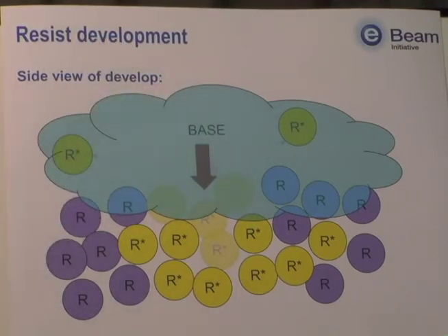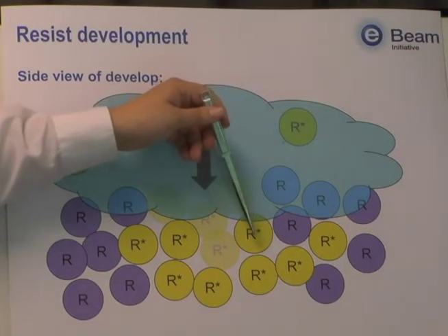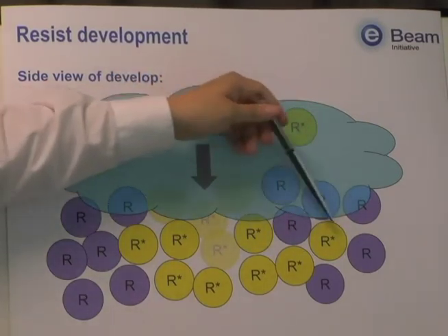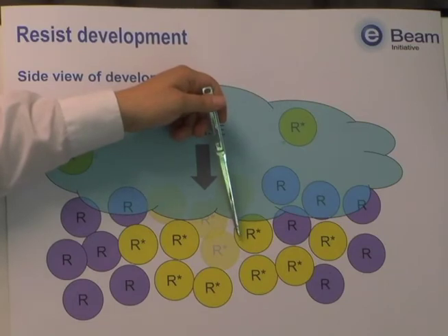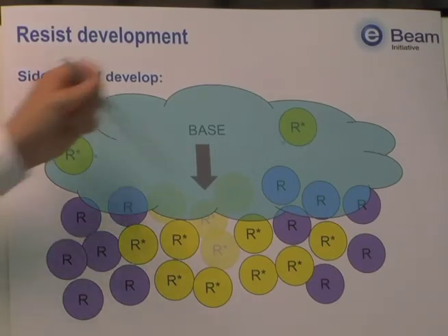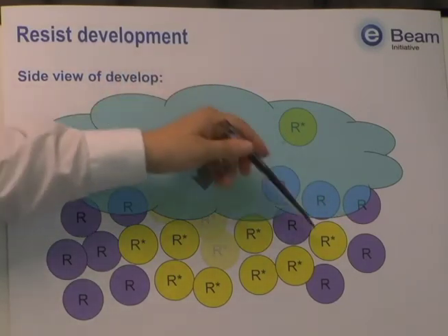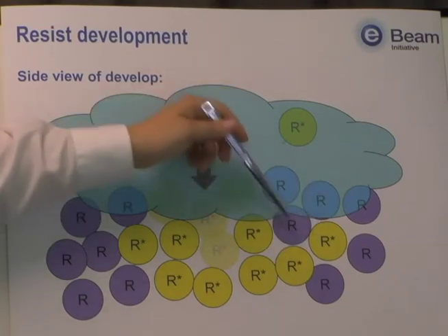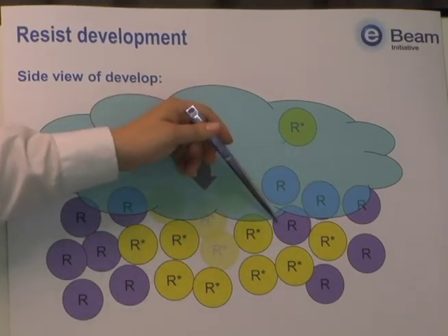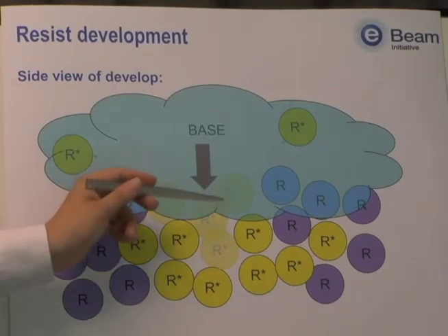Now, as an aside, this lateral rate becomes faster as the dose margin decreases due to a larger partially soluble length scale and the larger transition in the unexposed regions. Now, this can seemingly give rise to sublinear behavior in line linearity for small lines. What's also interesting to note is that a smaller dose slope results in more variance in the resist composition over a larger length scale, directly giving rise to increased LER. And you'll see this for any low contrast site.